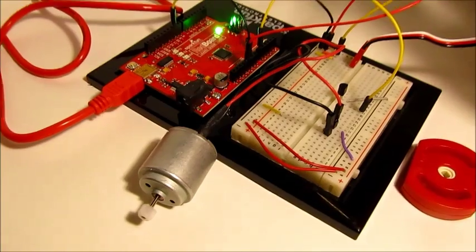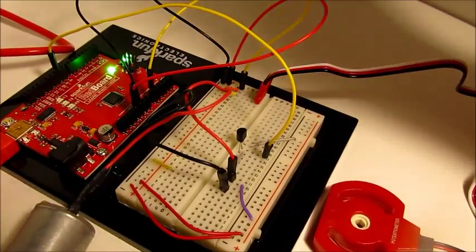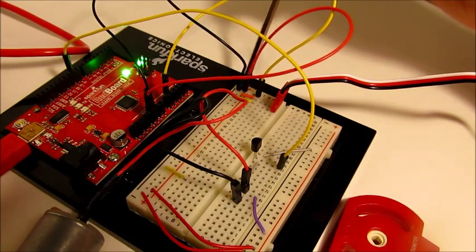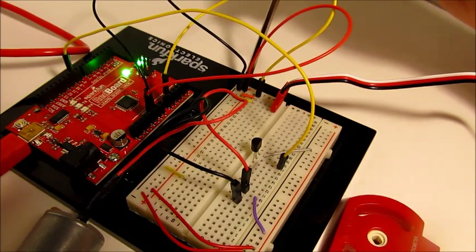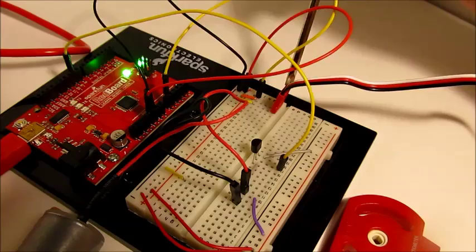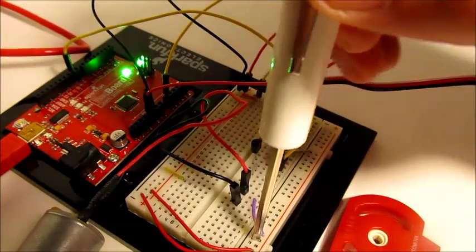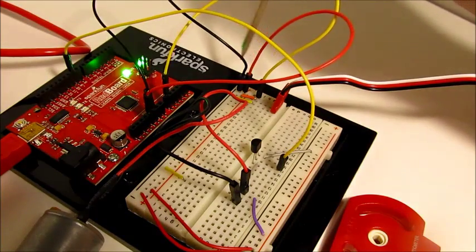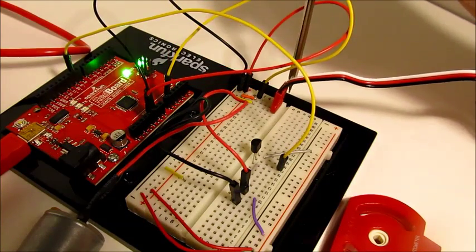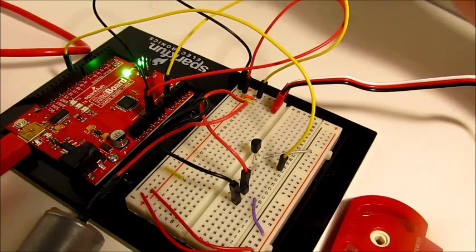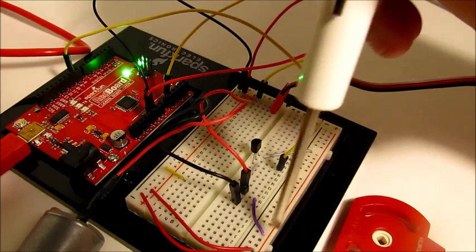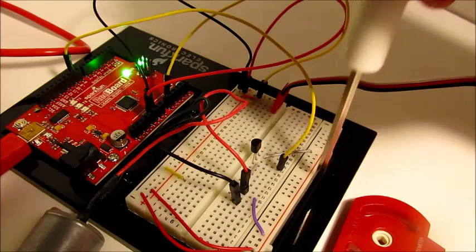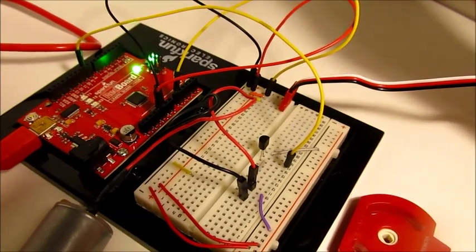Now the wiring diagram for this setup is power and ground coming from the board to the bus. This is mainly to supply the potentiometer power, but it's also to bring the ground for the transistor back into the same loop as the potentiometer and Arduino logic board. The motor and transistor are getting their main power from an external power supply, in this case a 9-volt battery.